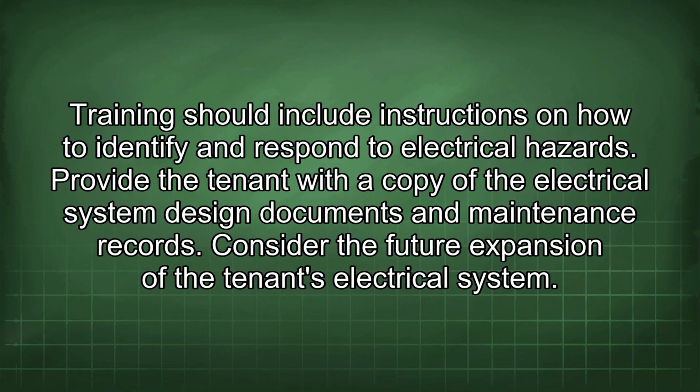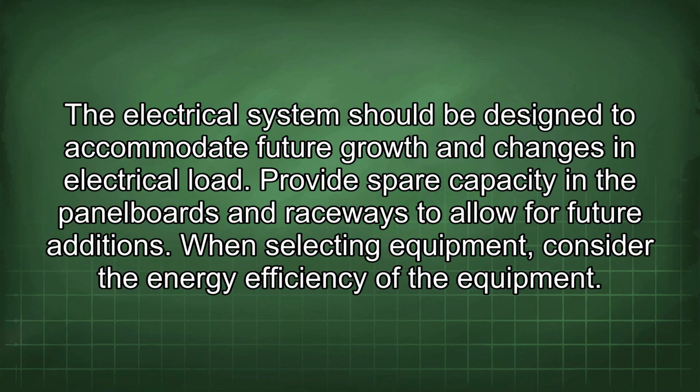Consider the future expansion of the tenant's electrical system. The electrical system should be designed to accommodate future growth and changes in electrical load. Provide spare capacity in the panel boards and raceways to allow for future additions.